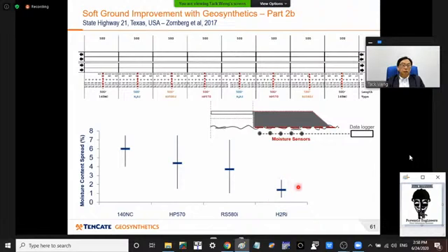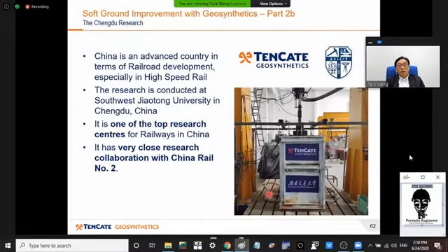ability to control moisture. And you can see here that with the H2RI, the moisture content spread is so narrow, as well as the mean or average moisture content. So it's been shown to be effective in preventing this edge cracking of pavements over expansive soils.